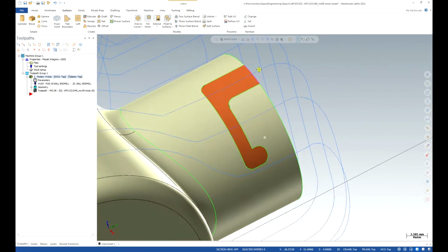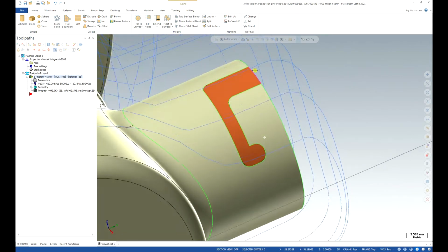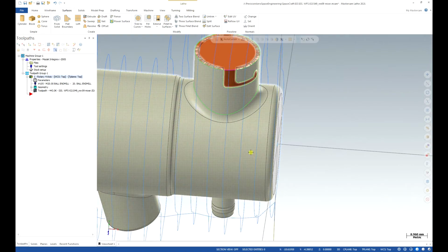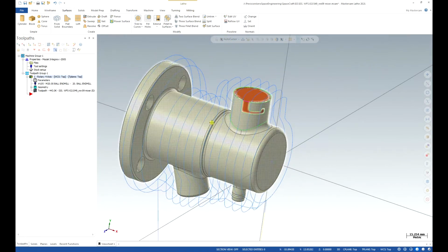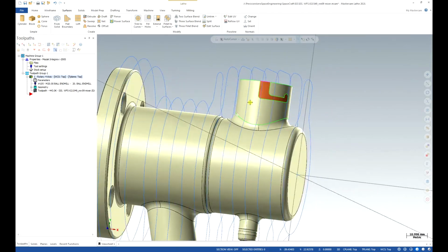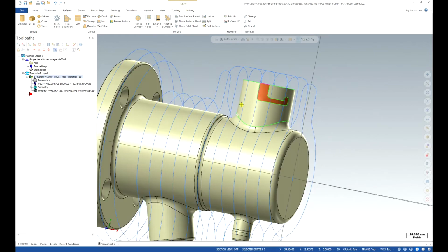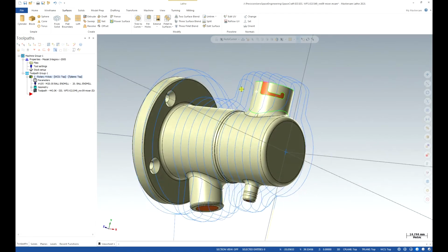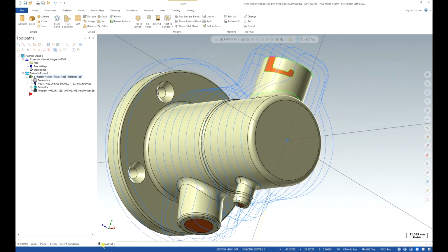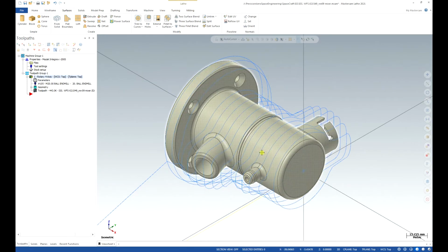Wow, the toolpath looks a lot better. There are no retractions or dodgy moves. All looks cleaner. So you can see how the quality of the surface can affect your toolpath. This toolpath is using the rotary cuts. I also want to show you the same toolpath with the axial cuts.